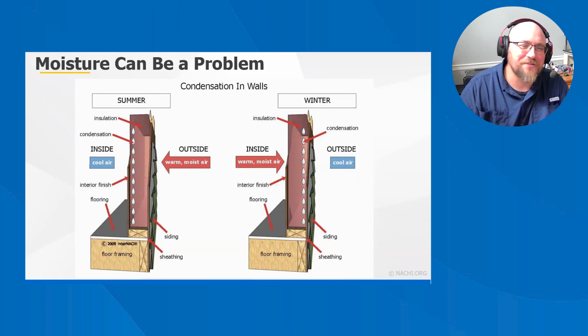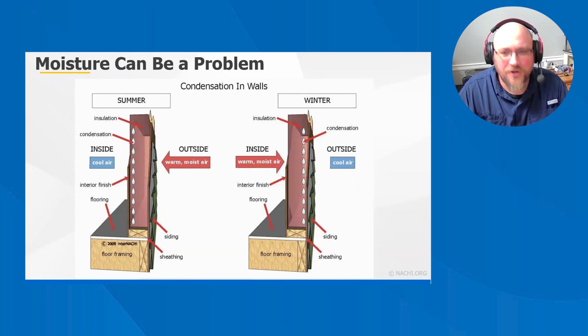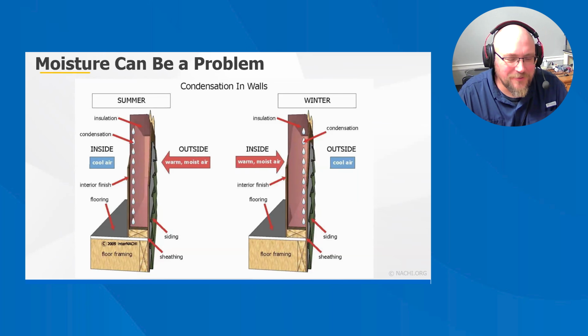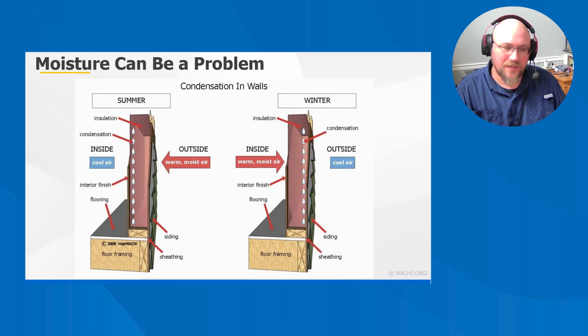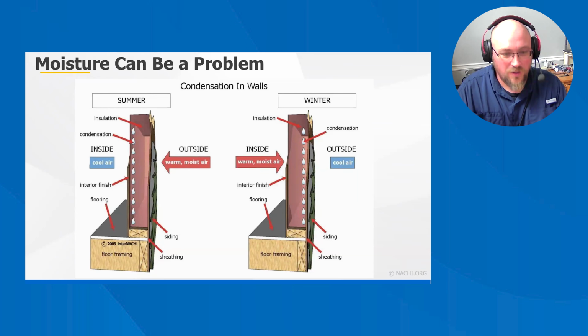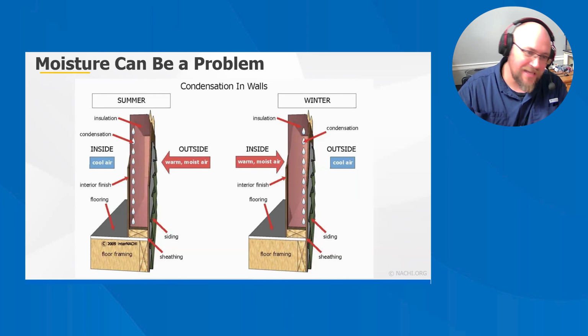That was their explanation to her, that water is condensing inside the house because you're using so much water in the house. And she didn't like that answer. It turns out the north side of the house, which is where their living room was, the baseboards at the bottom were getting condensation building up on them. The only thing we could come up with was that it's a north-facing wall, so we were getting the super cold Arctic blast air blowing against that north wall.